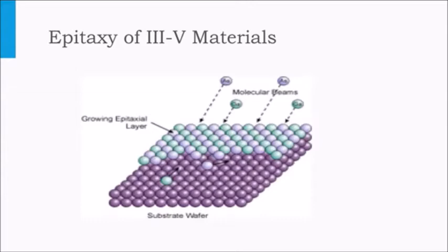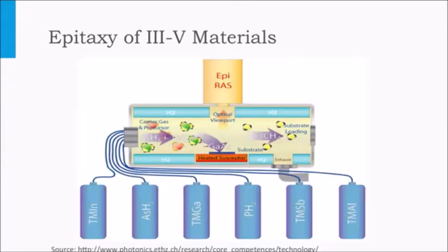The relatively slow layer by layer growth allows the deposition of compact materials without any vacancy defects. Furthermore, processing at high vacuum conditions prevents the incorporation of impurities. Dopants can be added to make it N-type or P-type. III-V semiconductors can be deposited up to a very high degree of purity.